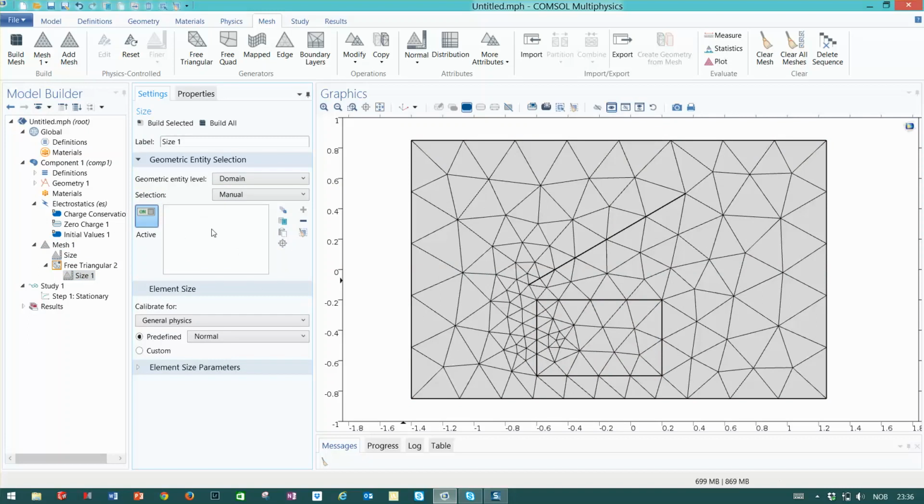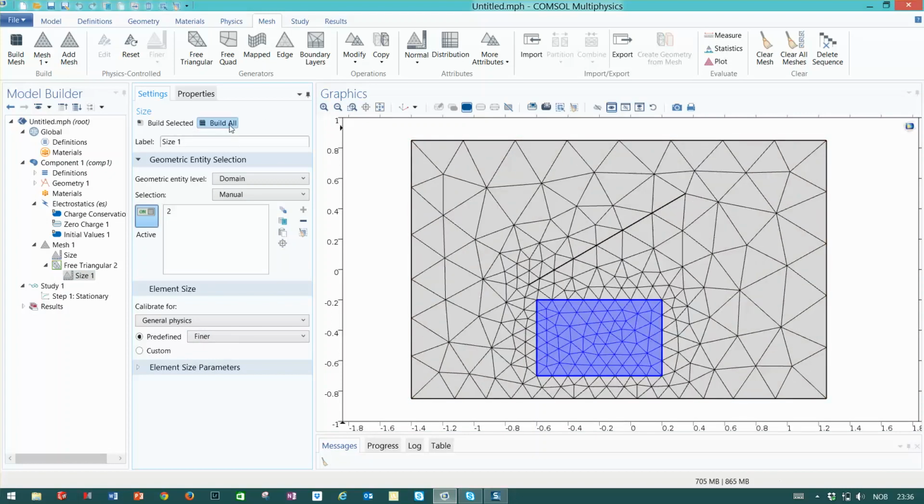Then it opens up to pick elements to be put in there. So I put in surface number 2. And then I can give commands to that size function. I can say, we have picked it manually. And then I go for a normal, no, we should go for a finer mesh there. Let's try. So we have a coarse mesh out here, and then we put a finer one here, just to try. See? This one is now defined to be a finer mesh.